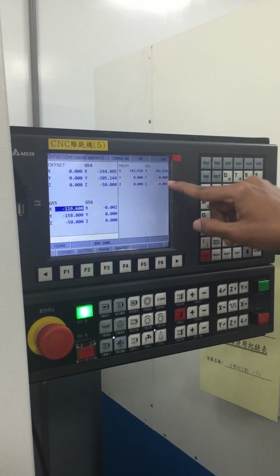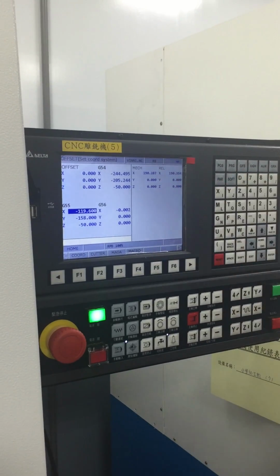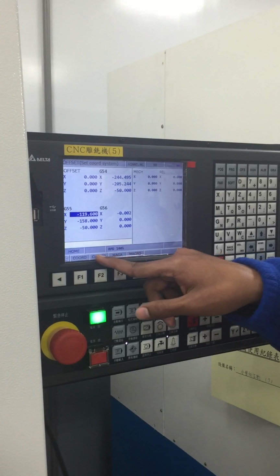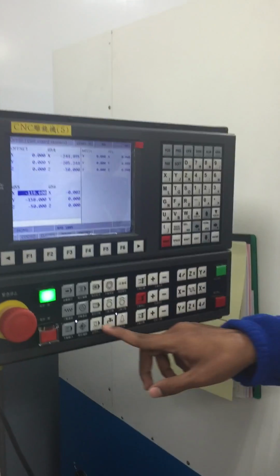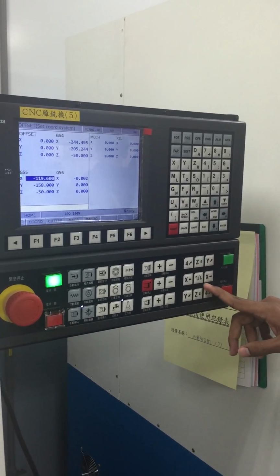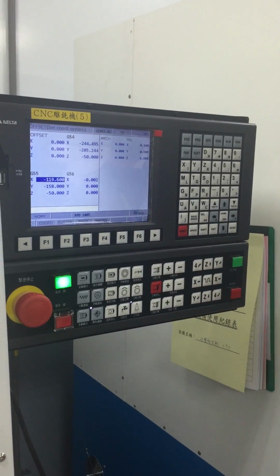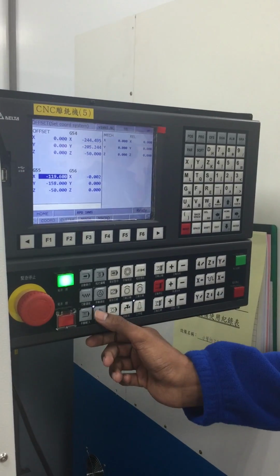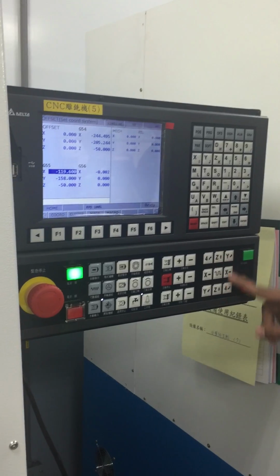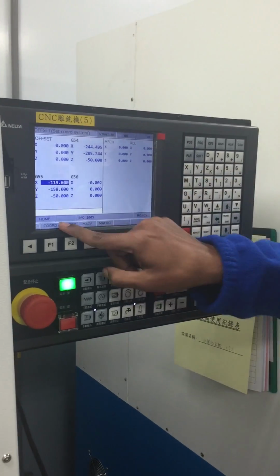So once the alarm is removed, you gotta wait until everything is... When we just press that, the green button. Oh, well, this one I just know is what a Taiwanese friend of mine showed me. Because sometimes when you press the green button, it doesn't work at times, so then you just press this, and then X, Y, X, Z, X, Y, whatever. Just make sure you press 3 of them and it will go back to 0. So that will turn off your alarm.